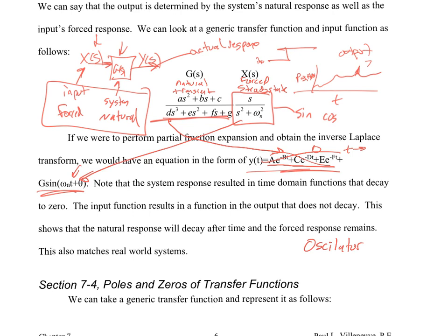So remember the Tacoma Narrows Bridge? You probably saw that in physics class, where it just kind of, why was it swinging so easily when the wind speed was not too bad? It's because however the wind speed was coming along, it was exciting it at its natural response. So there was very little damping at that specific frequency. So it would just swing back and forth without hardly any energy put into the system. And then once the amplitude got so high, it wasn't that the wind speed was picking up, it's just that maybe the amplitude, and I can't exactly categorize because I don't know exactly, then it started to swing massively, and at some point it fatigued and broke, okay?